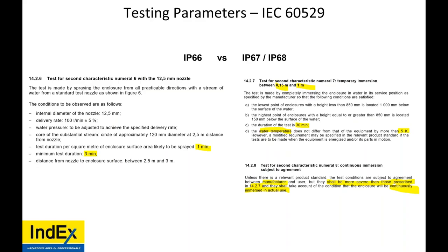Somebody asked or said that flameproof and explosion proof are the same. No, they are not. Different testing requirements. One is based off of IEC 60079-1, while the other one is UL 1203. So this is going outside of IP ratings, but they are not the same.